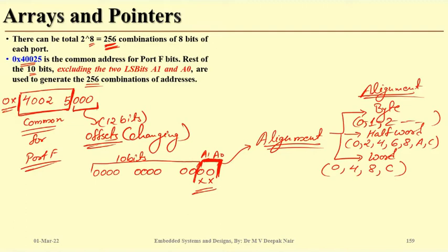When we are using an ARM-based 32-bit system, they always avoid the last two bits to allot the memory for full words. So because ARM uses this alignment approach, the last two bits are not used to generate any pattern.